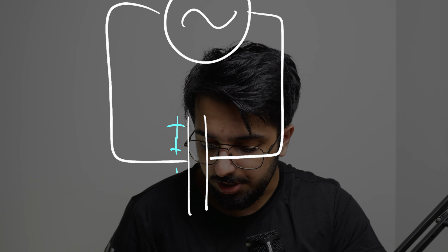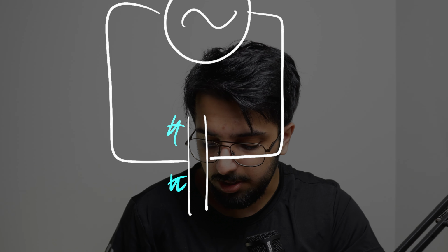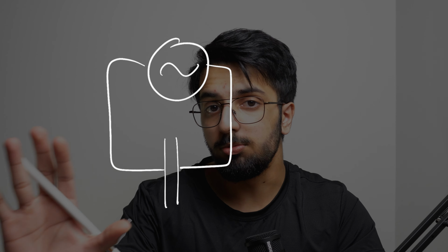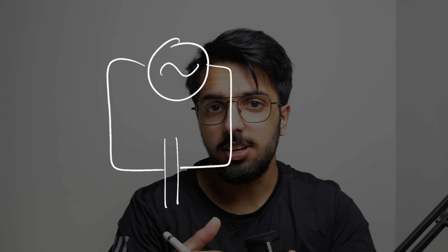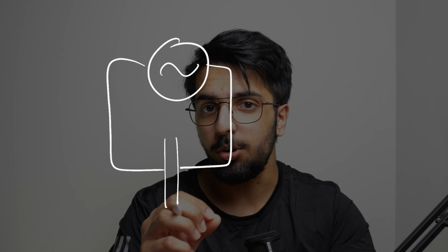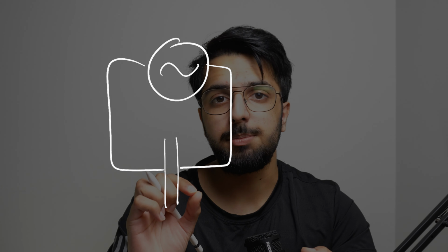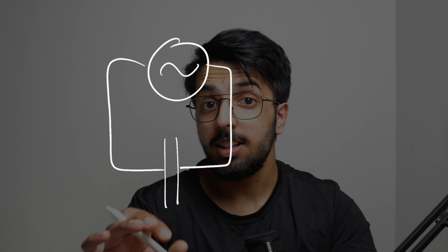And so this prevents large amounts of current from building up, okay? So it prevents this process of large amounts of current building up on the plates. And because we know it is the large amount of current that builds up on the capacitor plates which causes the capacitor to resist oncoming current, if the frequency of an AC power supply is high and therefore the charge cannot build up on the capacitor plates, the capacitor is going to resist current less.